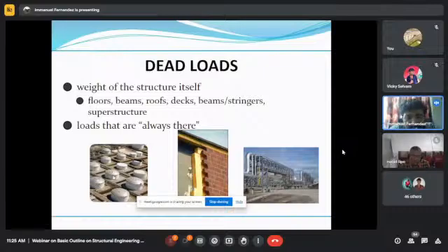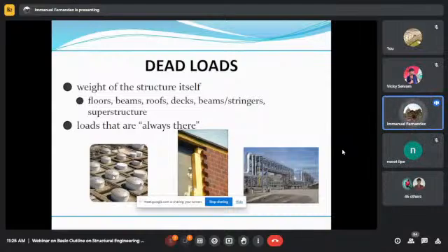And these industrial structures are prone to fire. So what we have to ensure is our structure is resistant to fire for at least a minimum of 2 hours. And we ensure that the steel structures are fireproofed, coating of fireproofing has been done, as per the OISD standard. OISD 164 is the standard which we use to ensure that structural steel is resistant to fire. Like in case of any fire, there shouldn't be any major collapse of the equipment or any death.